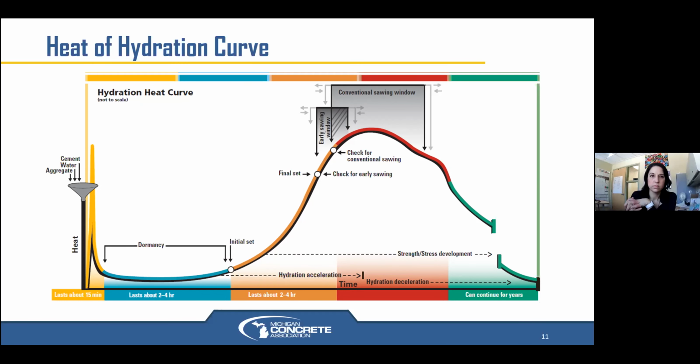What other agencies around the country and MDOT, which never really did it extensively, have found is that skewed transverse joints have kind of fallen out of favor with a lot of different agencies. They've instead switched to dowel bars to provide load transfer. The issue with skewed joints as far as performance is they don't quite perform as well as doweled joints, but they are fairly close, with obviously less cost because you don't have the steel dowels in there. But for very high traffic roadways, you're going to need a more positive way of load transfer, such as the dowels.